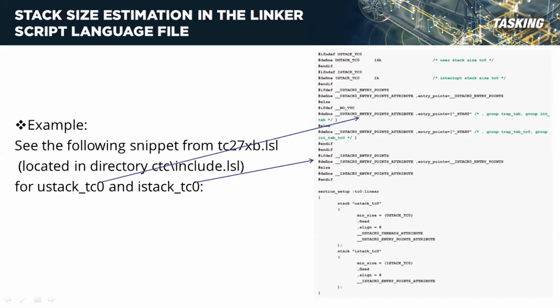When a certain interrupt or event happens, the context for this task needs to be saved before jumping and executing another task or another interrupt. This is basically the definition of context switching: I'm switching between different contexts. And after I have executed the interrupt, for example, I have to restore the context that I saved inside the context save area. That's why it's called context switching.